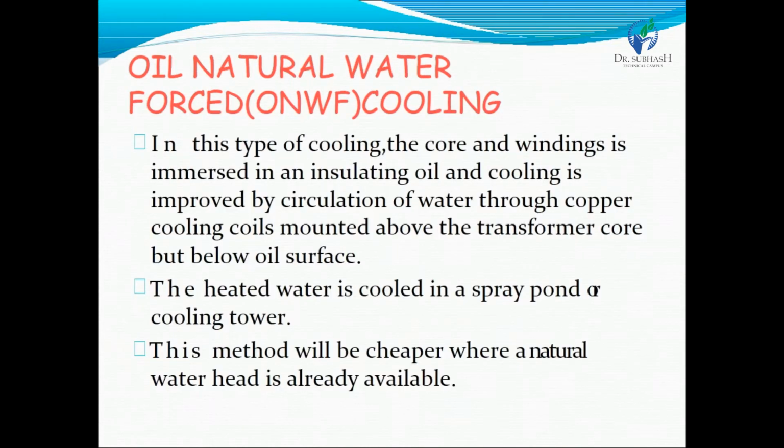Now the topic is oil natural water forced cooling. In this type of cooling, the core and winding are immersed in the insulating oil and cooling is improved by circulation of water through the copper cooling coils mounted above the transformer core but below the oil surface.